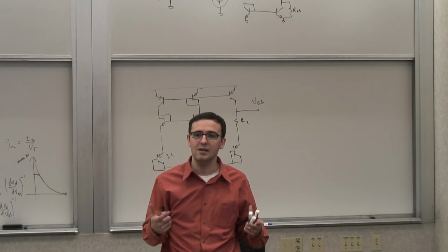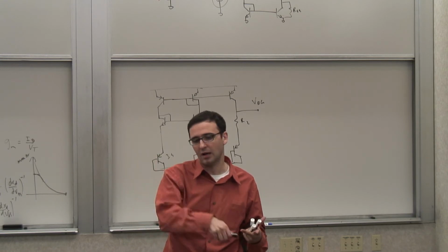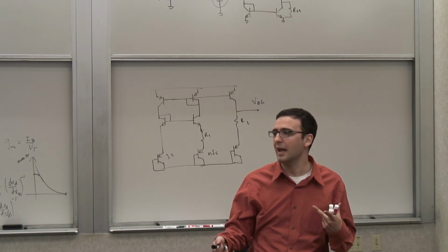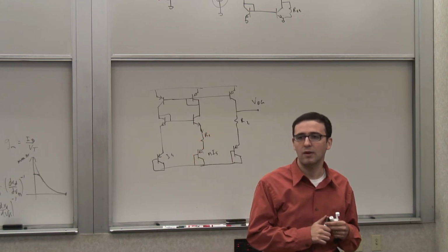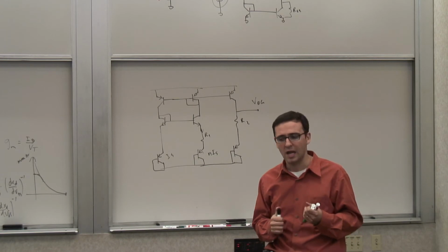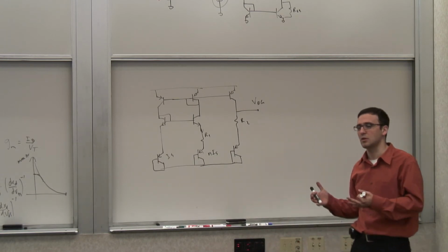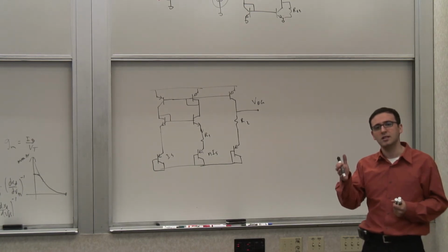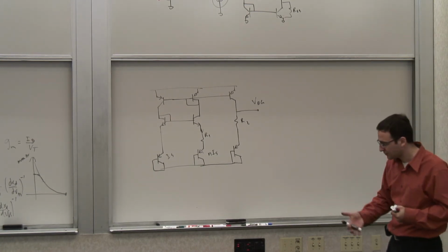Or, if you want to get the gain, you have to bite the bullet and say, well, okay, I'm going to tolerate a smaller amount of gain, a slower speed, and increase my impedance if I want to maintain my current consumption. And then we saw all those trade-offs in different examples. We looked at different op-amps and some numerical examples. We did some, and you verified some of this with SPICE, looking at your simulations.